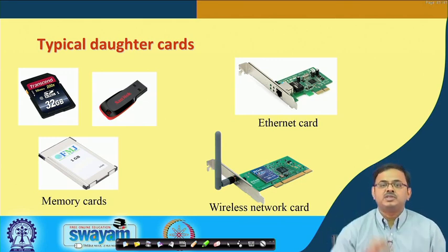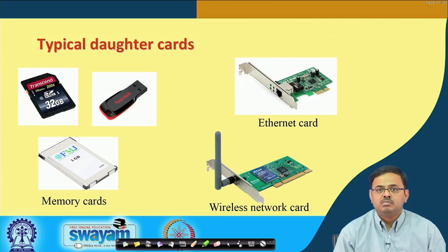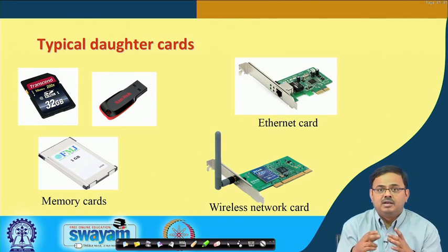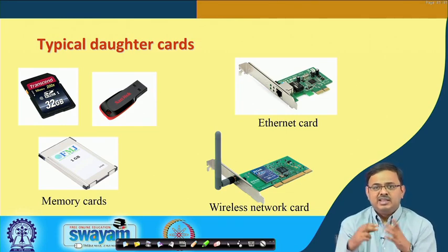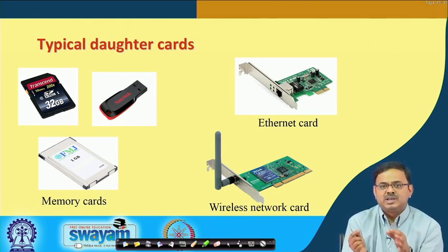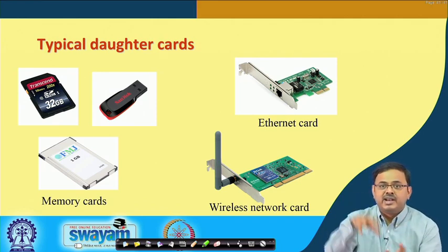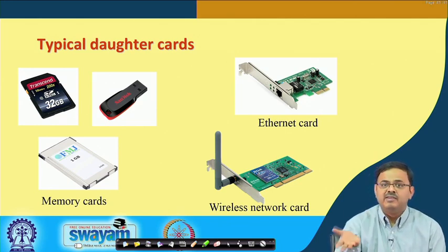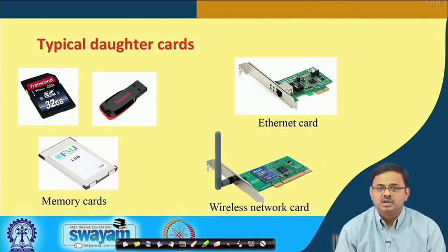Okay. Started with a piece of silicon, level 0, coming out from the silicon wafer. Level 1, put it on the chip carrier, had the substrate, and finally, wire bonded the chip to the substrate, everything done, and the substrate also has these interconnections ready to be connected to the motherboard. That is where we stopped at level 1. Level 2, we went ahead and looked at motherboards.